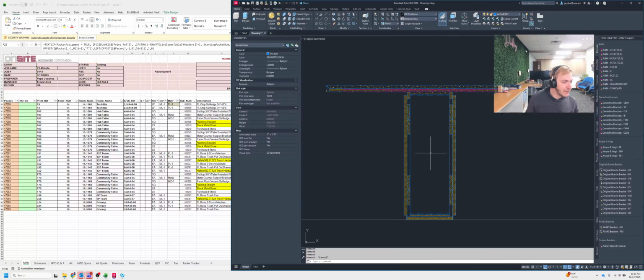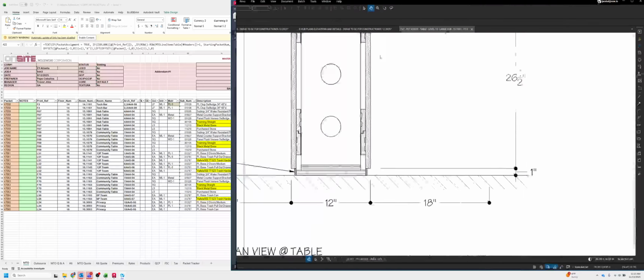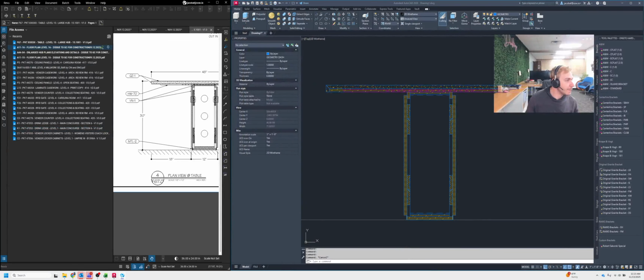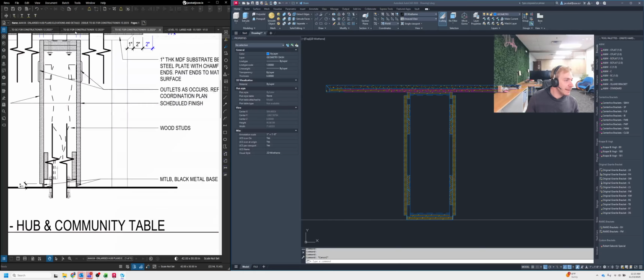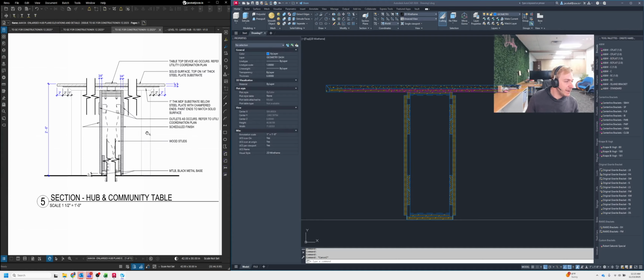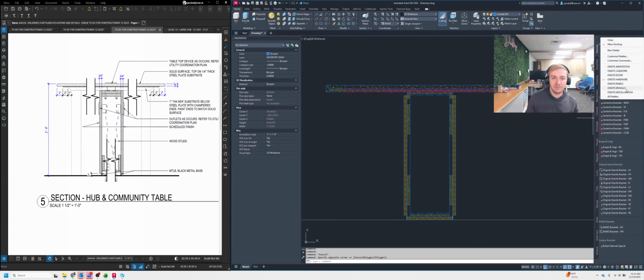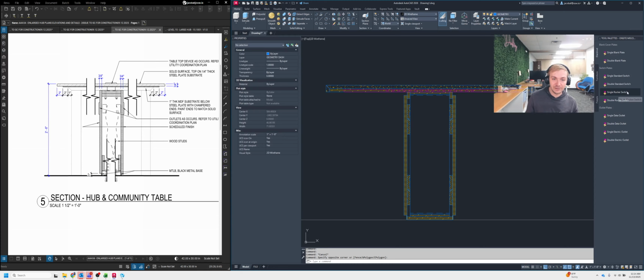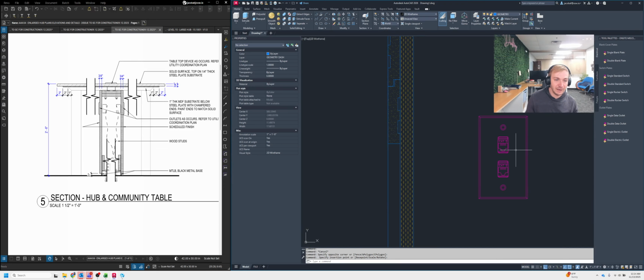All right, moving on. Let's see what else we got here. So let me bring back my Bluebeam here. Sorry about that. We have outlets to add, and we are also going to add in the wire chase too. So outlets are real easy. You want to make sure you have them exactly where they want them. So we're going to go to on-site miscellaneous to pull those outlets. There's several different variations of those. Doesn't matter if you pick the wrong one by mistake, because you can always toggle it to show the correct outlet that you're looking for.